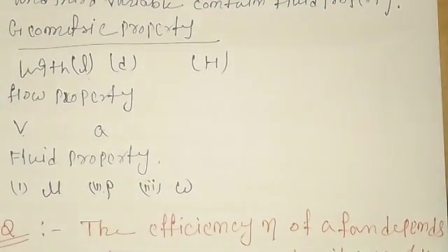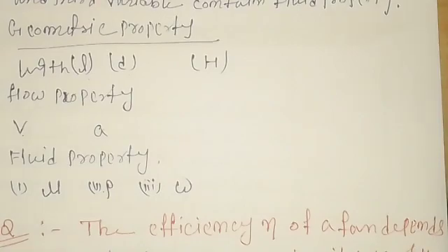So this is the theoretical way of solving a dimensional problem with the help of the Buckingham pi theorem. First of all, you have to find out how many variables are involved in the problem, then find out the pi terms, then select the repeating variables, write down those pi terms, equate the dimensions and find the arbitrary powers, and substitute again into that equation to get the relation. We will try to understand this whole concept with the help of a working example.